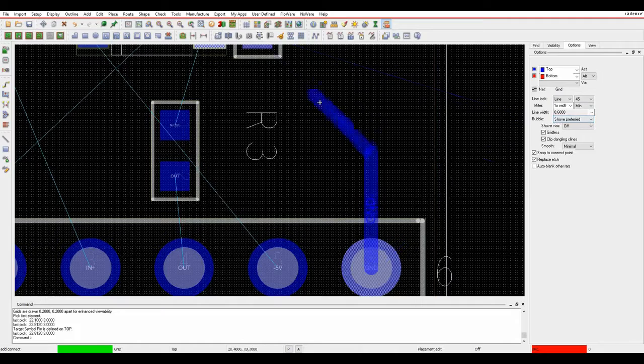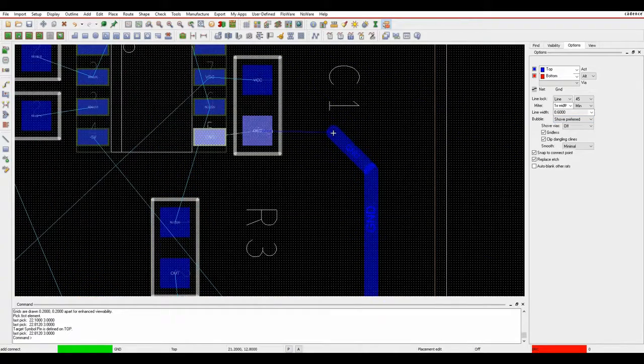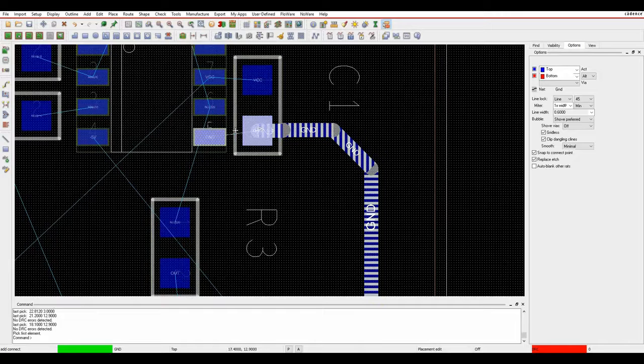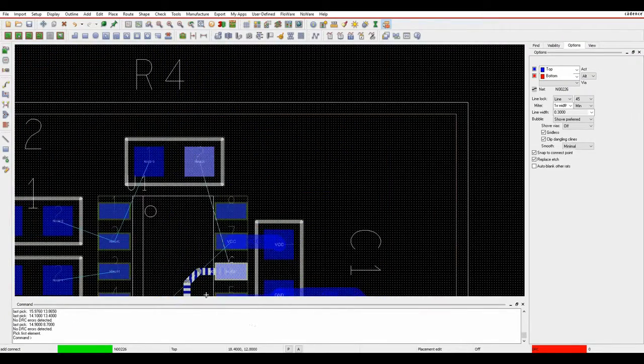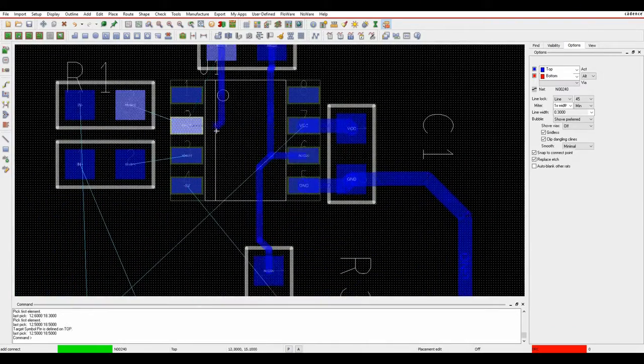It's using the default line width for the power. And we can come on, make a connection, make a click to join the routing and start routing this way. So very quickly you can see I use this one. It uses a thinner track, which is the 0.3 thick track. And we can come down, just come out something like that, and route down to the bottom. And then we'll take it from this segment. So we'll just go ahead and route the board as we need to.